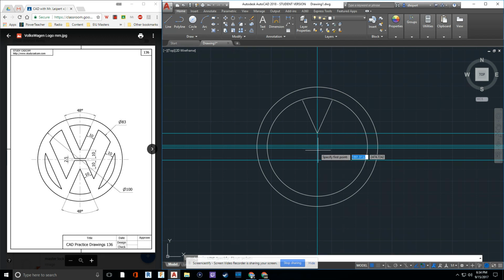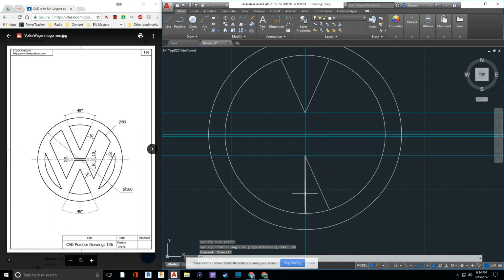Cool. And once again, since maybe you don't know how to use the mirror command yet, I'm just going to draw the same thing on the bottom. We'll click on that line. You can just click on the rotate command, and we can go over 24, enter, and we'll do the same thing again, but we'll do a negative 24. Select it, RO for rotate, snap over negative 24. Whoa, did it go to the same place? I didn't hit enter. Rotate, boom, negative 24. There we go. We've got this wedge. We've got that wedge.